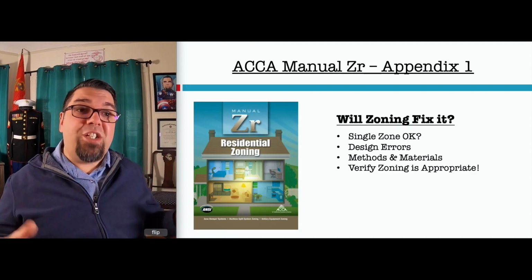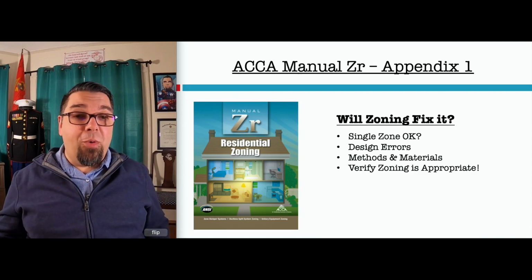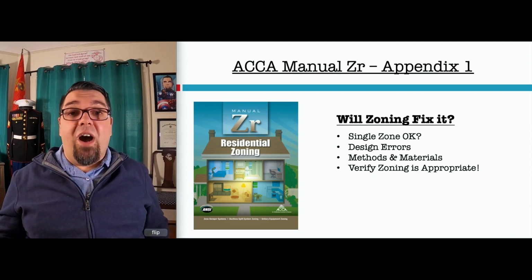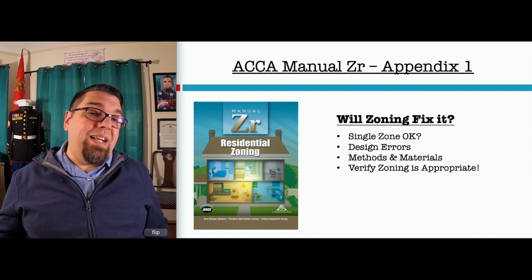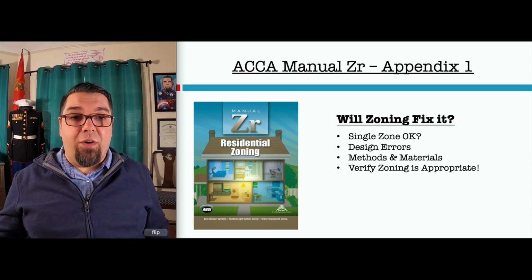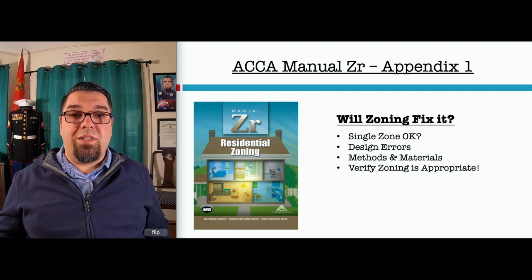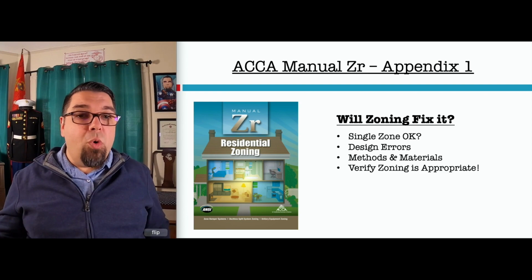To answer the question, will zoning fix it? Well, I think you're gonna find it's not always the answer, all right? Now, if it's a single zone system, I gotta tell you, there's many better ways to fix issues in a house than to zone out a single zone system. Single zone systems, I'm gonna be honest, it's just old technology and an old way to heat and cool a home.